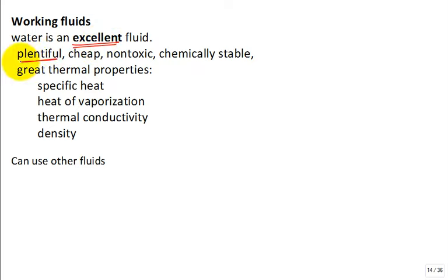That's one reason it's a good choice. Not just because it's cheap. It's very cheap. It's non-toxic. Think about that. There's a lot of other working fluids which you don't want sprayed over your body. It's very chemically stable, which means you can pound it up in pressure and pound it up in temperature, and it's not going to disassociate because it is H2O.